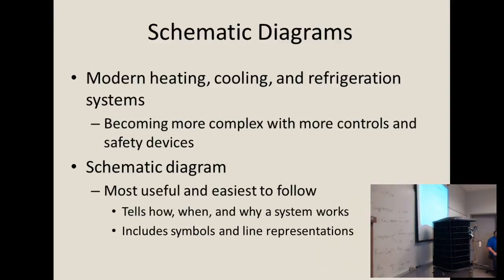Yeah, to the common on the compressor, to the common on the fan motor. It may be that you have a terminal, that's what I'm saying, to the common. If it's a wire, that's cool. Okay, step 3. From T2, not T1, T2 to the runs.